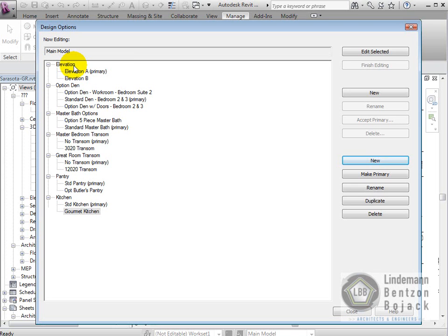But if you're uncomfortable or not sure on a view that comes up that's going to be deleted, just uncheck it. You're better to be safe than sorry because you might finalize everything and then find that it deleted something that you needed. And at that point, you pretty much have to start over. You can't really undo all of this finalizing.